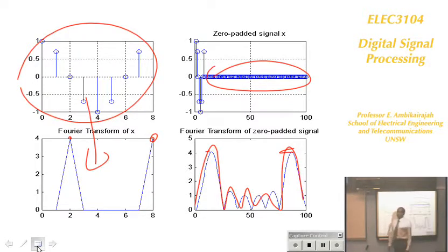So, summary: FFT is the way to go, and make sure your number of samples is a power of 2, then the fast Fourier transform can be applied. If you don't have a power of 2, MATLAB will add extra zeros to make it a power of 2 so that it can run faster. The discrete Fourier transform gives you frequencies at discrete frequency positions, called k, which are multiples of the resolution.